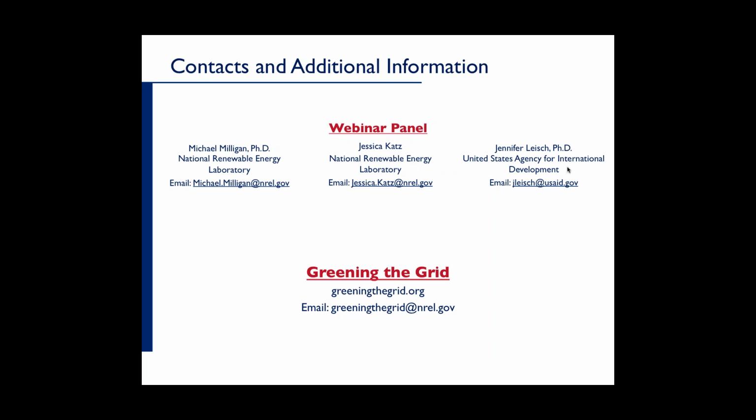And we did find the dispatch changed a little bit, the cost changed a little bit. But the other thing we did was we got actual emission curves from every generating unit in the Western interconnection, for every thermal generator. We got that based on empirical data, and that empirical data shows what happens when the plant is started, when the plant stopped, when it's turned down to a less efficient point, when it ramps up, when it ramps down. All of those things were captured in our modeling.